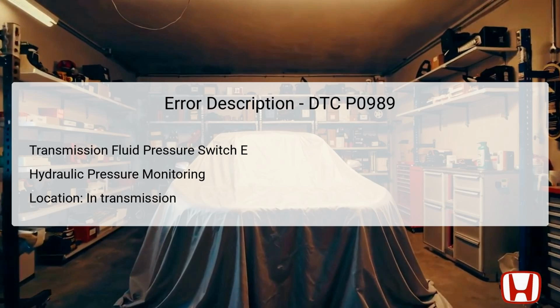When the hydraulic pressure is supplied, the switch activates, turning on the signal to the PCM, which enables a smooth transition into 6th gear. If the hydraulic pressure is insufficient and does not engage the 6th clutch, the switch remains off, causing the PCM to suspect a fault. This condition can be critical during gear changes, as improper functioning may lead to harsh shifting or potential transmission damage. The switch is typically located within the transmission assembly, where it can effectively monitor and manage hydraulic conditions.